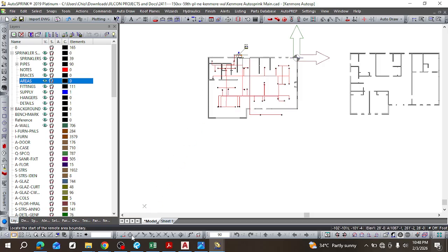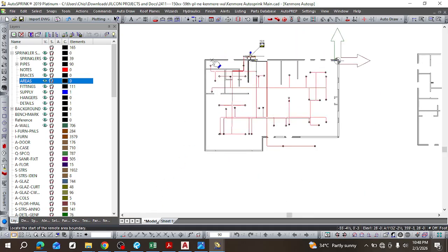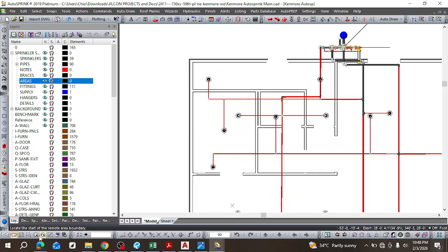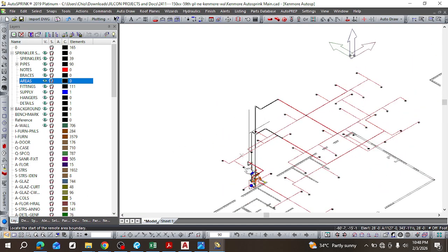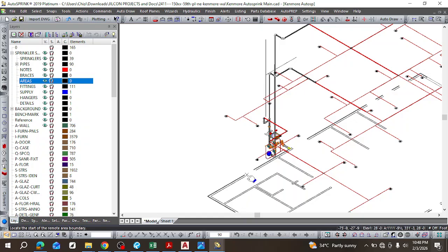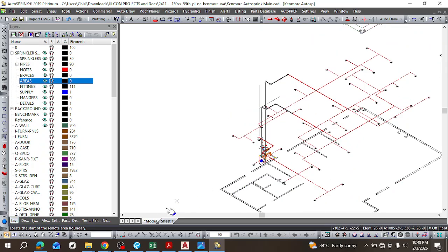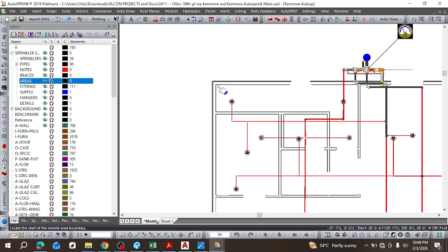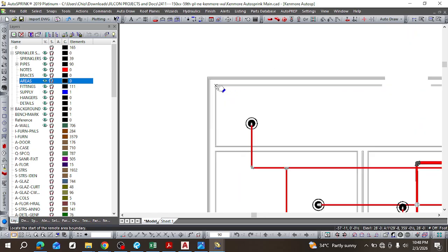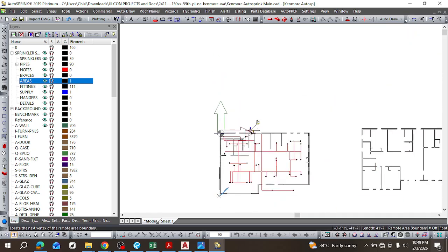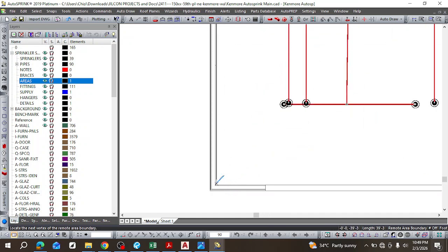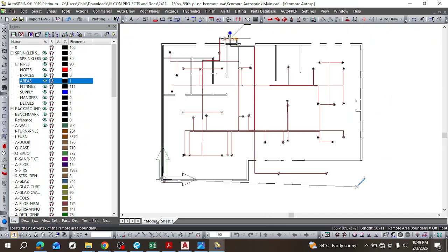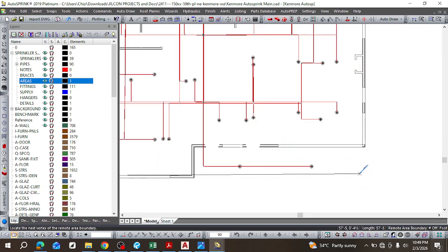Now, the snap we were using before is going to be an enemy to us now because this wall is actually on the bottom floor. So if you use that snap, it will snap to this height, right? That is, when we turn this on, but we don't want to use that. We want to just use the silhouette of it to draw our line. So I'm not going to turn it on. I'll just mark the inner points, right? By marking from up here, being that the snap is off, it's not going to mark those actual points, right? It's just going to hover at that height I've specified, right?